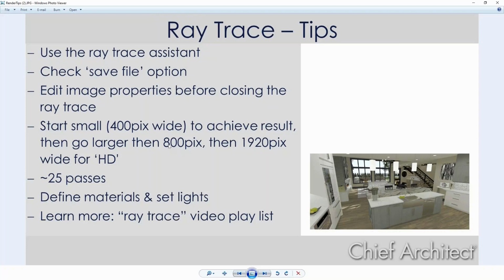Okay, so I was thinking to upgrade my graphics card, but it doesn't look like I need to. Yeah, ray tracing will not use your graphics card. The standard rendering that we use uses your graphics card GPU. Ray trace rendering uses your CPU, so having the fastest possible CPU for ray tracing is probably going to be your best bet for speeding it up.